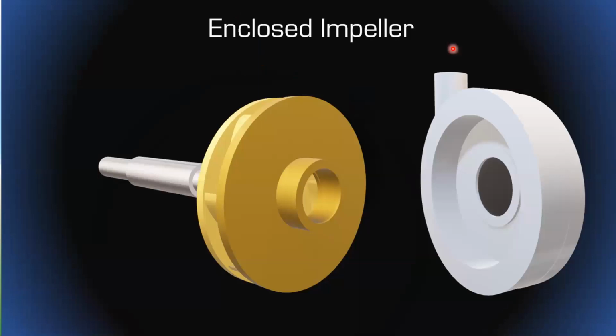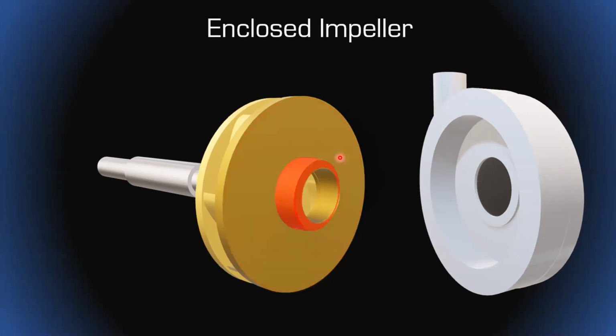But before we look at that, let's look at the actual wear component here. All this flow is going from the outer high pressure portion of the impeller back to suction. And it first has to go through the face of the impeller and also the face of the volute itself. If you can imagine, that is quite a large surface area. So this flow really doesn't wear away a lot at this location, because it's such a large area. The location that's really going to see the wear and tear is around this front area right here. All that flow has to go over that small area, therefore increasing the wear.